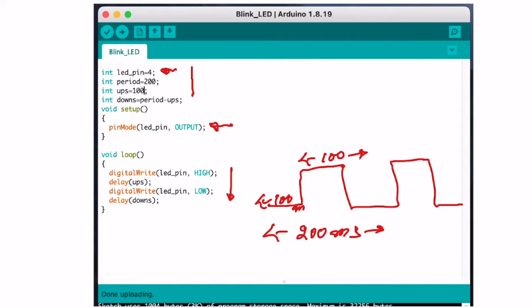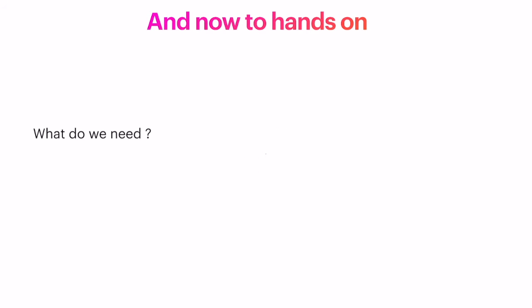It essentially looks like continuously glowing. Here we have used a duty cycle of 50%. We can change this based on this variable and see how the LED brightness behaves. We have had enough of theory. Let's get some hands on.